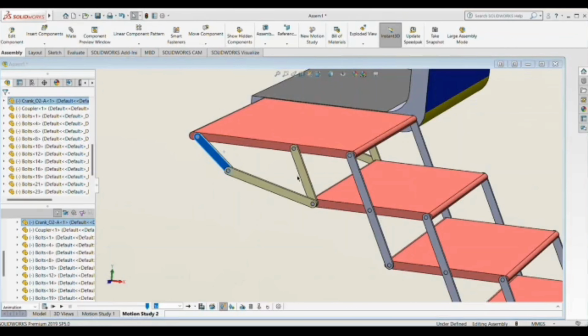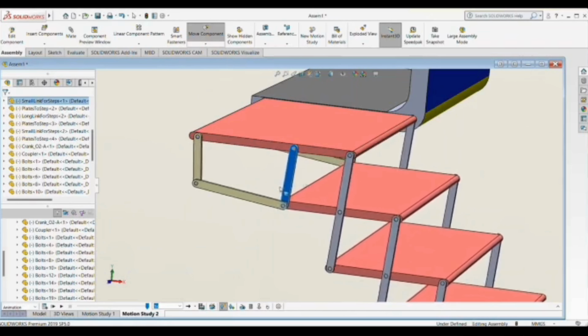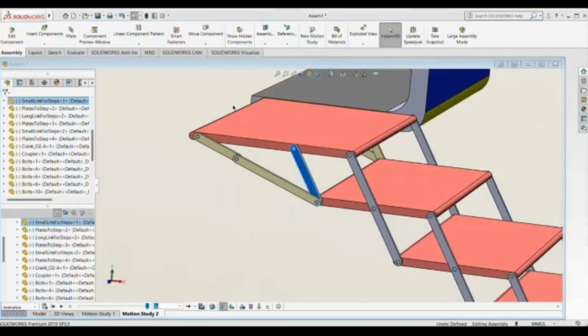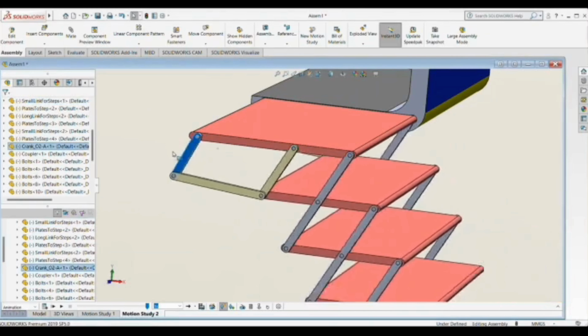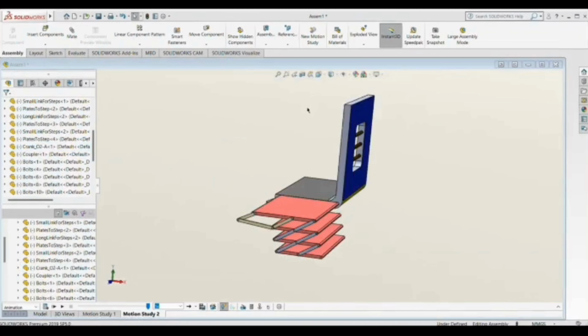In this mechanism, the rocker has two fixed pivot points, so it oscillates within a defined range. When it reaches its extreme position, the railway steps stop moving, allowing passengers to board and alight safely. The crank is motor driven, providing uniform and controlled motion. We have chosen a step size of 80 cm, which we found to be comfortable and safe for all the passengers. To make it more real, extra outer parts were added around the crank.